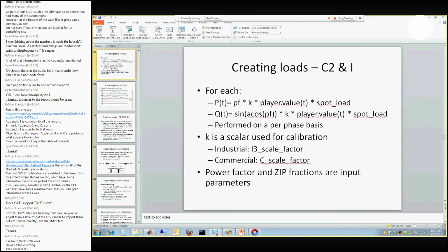Yeah, I think there are so many different standards for that, especially when you start looking at it from SCADA data. Is that the stuff being injected into the transmission side or drawn from it? Then your sign could be reversed. So we tried to make it as close to standard notation as we could, treating it as flowing down from the substation, so your load would be pushing that back up. And your lagging should have a negative power factor, right? Yep, exactly. Okay, that's the way we've been interpreting it.